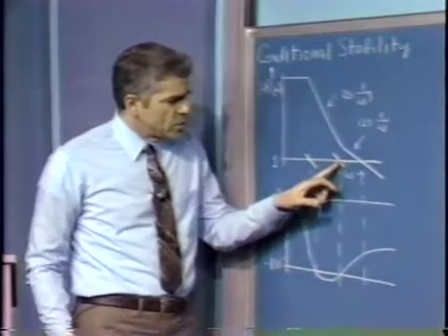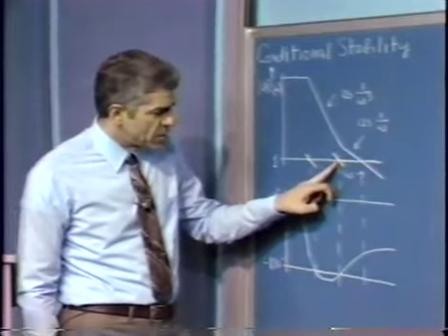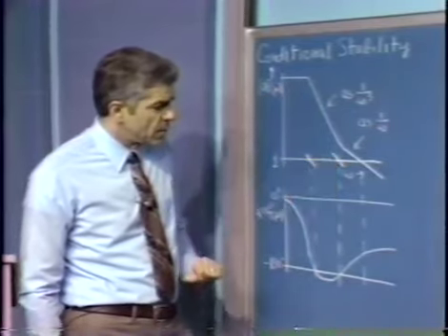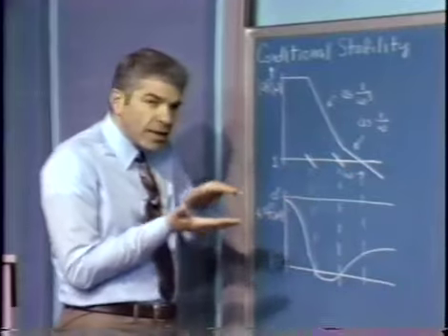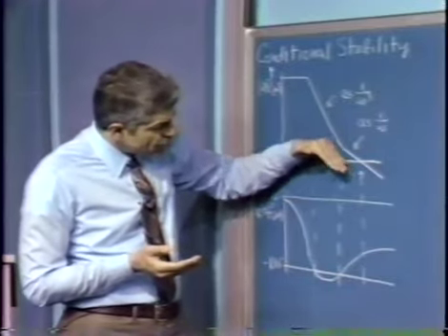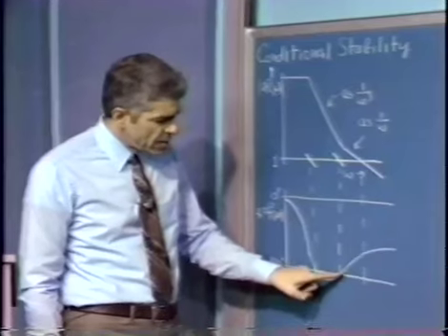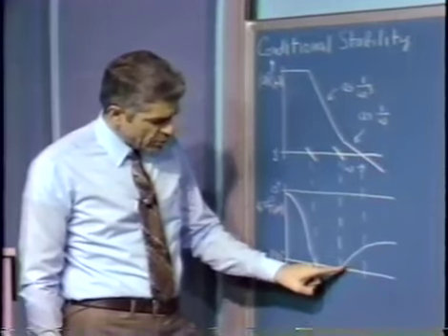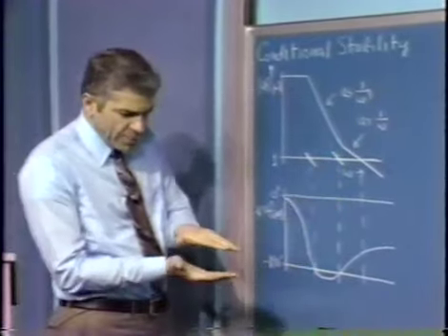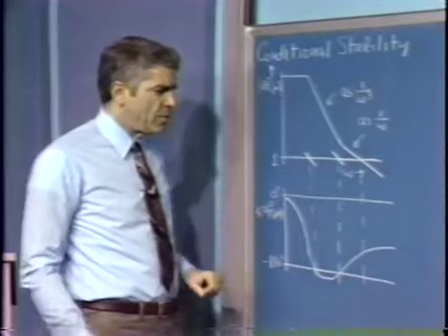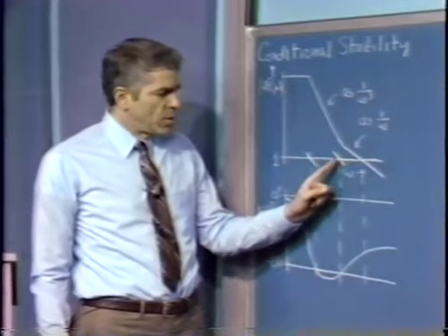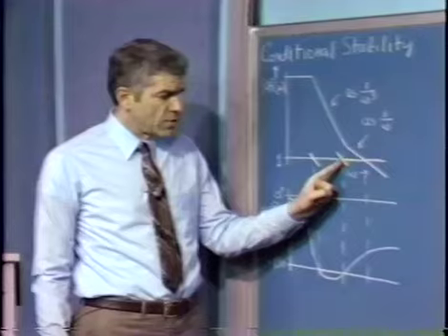Conversely, if we assume the system was oscillating at this frequency with the amplitude necessary to force unity magnitude or crossover at this frequency, and now we assume that the amplitude of that oscillation shrinks just a little bit, the magnitude curve is pushed up. We cross over at a slightly higher frequency. We cross over, therefore, in a region of positive phase margin. The system, again, the amplitude further decreases. The system's stable. The amplitude further decreases. Fine. So we conclude that we really can't get a stable amplitude oscillation with the value of E necessary to force crossover at this frequency.